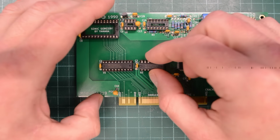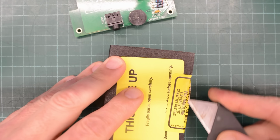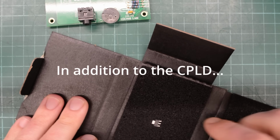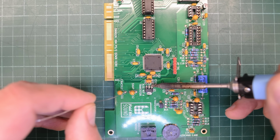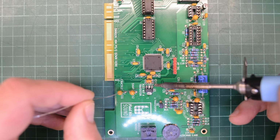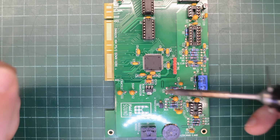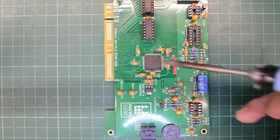I just ordered the available bill of material. Oh, I completely missed that this board has one surface mount component. Good thing I didn't wash the board. This would have been slightly easier to solder before I install those caps, but not a big problem. If you're playing along, you may want to solder this component in the beginning when you solder that chip.